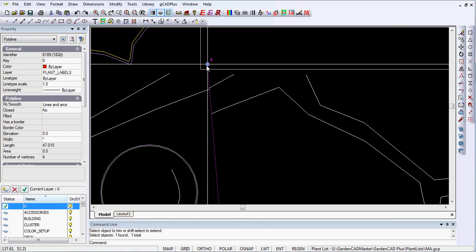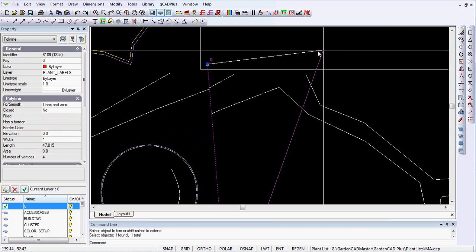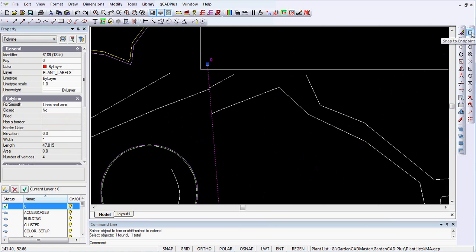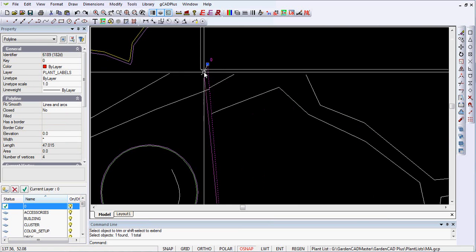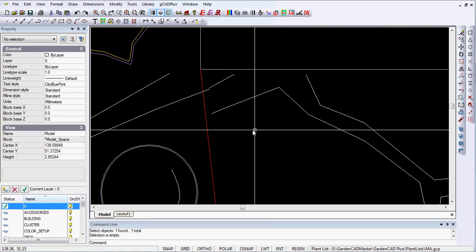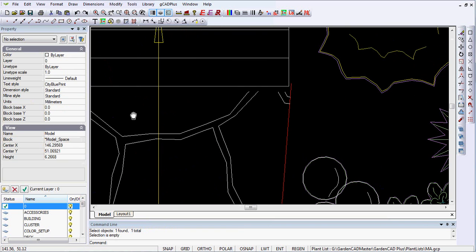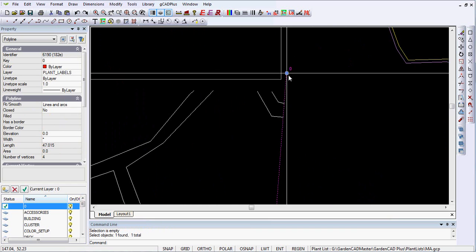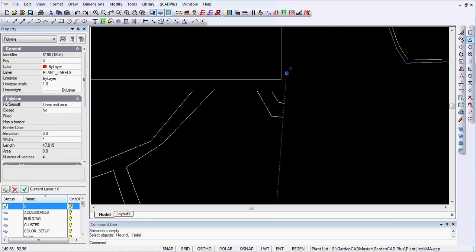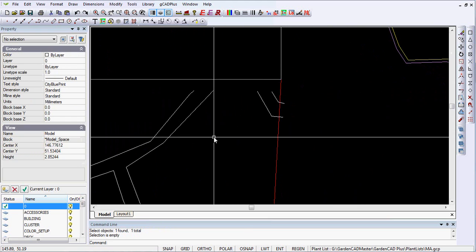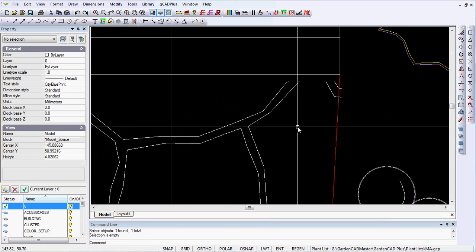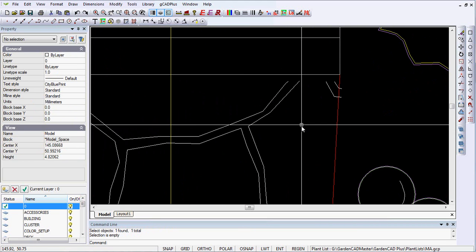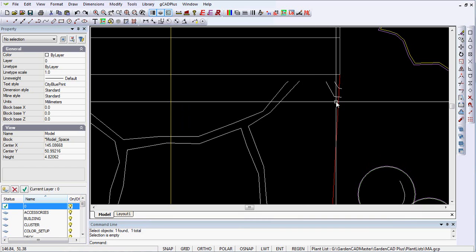So you can just click on the handle there, come over here to the object snap, and snap to an endpoint. Now the end of that polyline meets the way we want it. And we'll do the same here. Click there, come across. We could go to an intersect and latch that intersect. In that case, an intersect and an endpoint worked well.